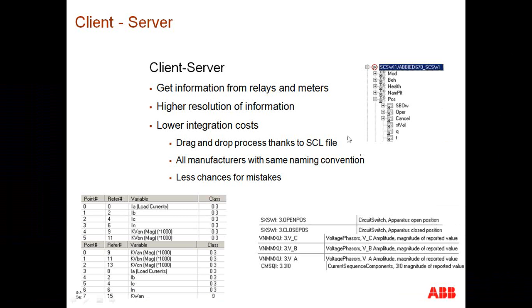So now, thanks to all of this, let's talk about the first protocol that we'll discuss as part of 61850: client server. We now have this substation configuration language. We now have the standard naming convention, which makes integration and engineering much simpler. Client server really represents a way to exchange the information that's part of the data model from the IEDs over to a centralized location: gateway, HMI, RTU.